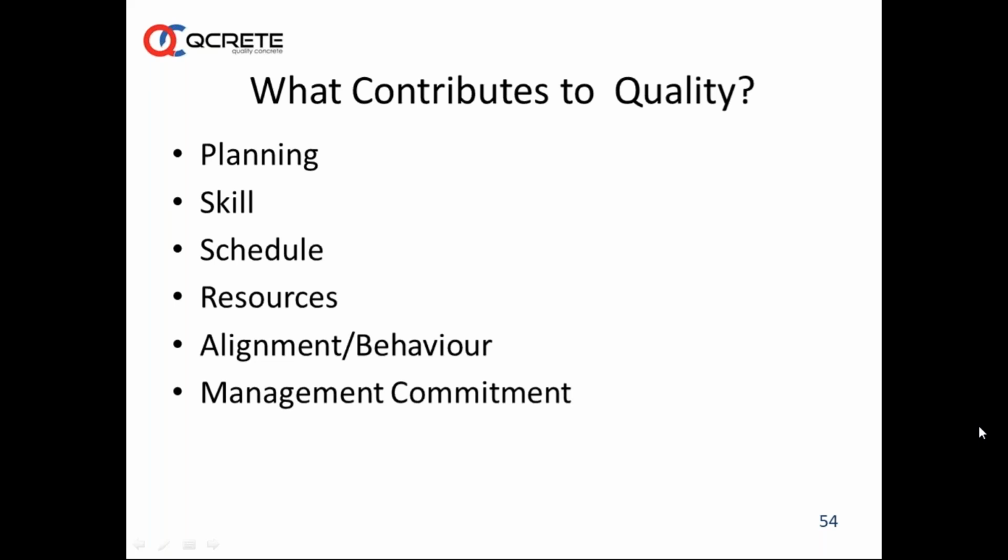But at the same time, you need to understand a very simple fact actually, that each QSM system will guide a particular family of mixes. For example, OPC GGBS mix will have a different family of mix. OPC fly ash is a different mix. OPC mix is different, and then in OPC GGBS mix itself you have different proportions. 35 is to 65, 35% GGBS, 65% OPC. That mix, if you are feeding into the QSM system, it should not include another mix which is 50-50. So these things have to be controlled, and most importantly, uniformity in the inward materials is important.